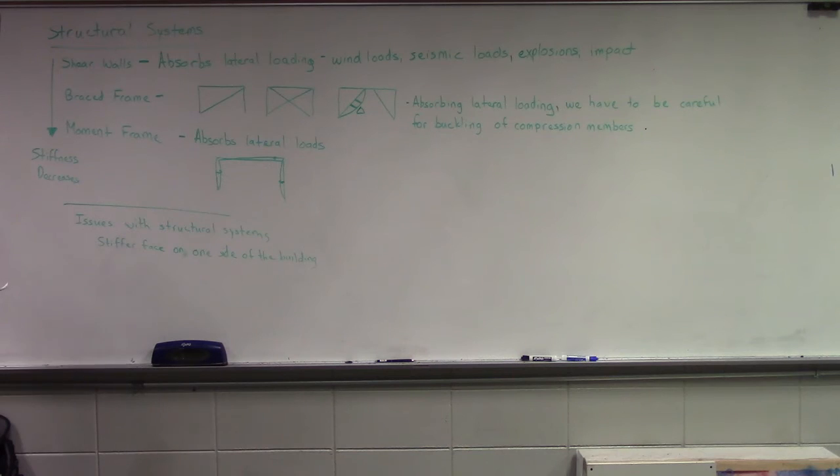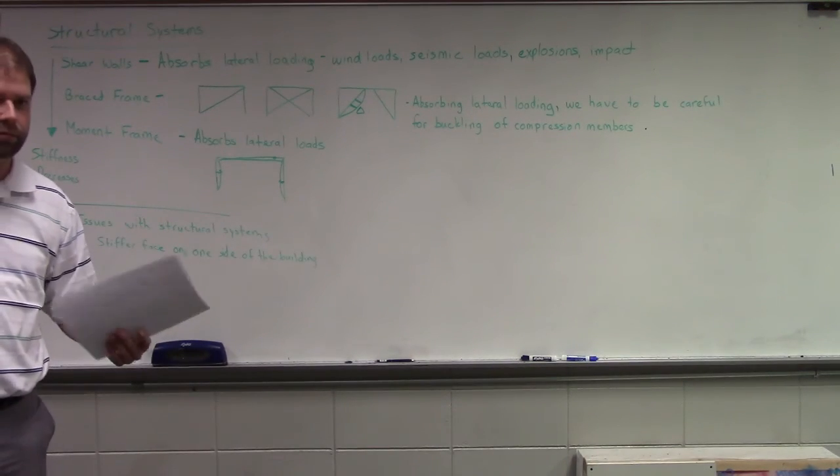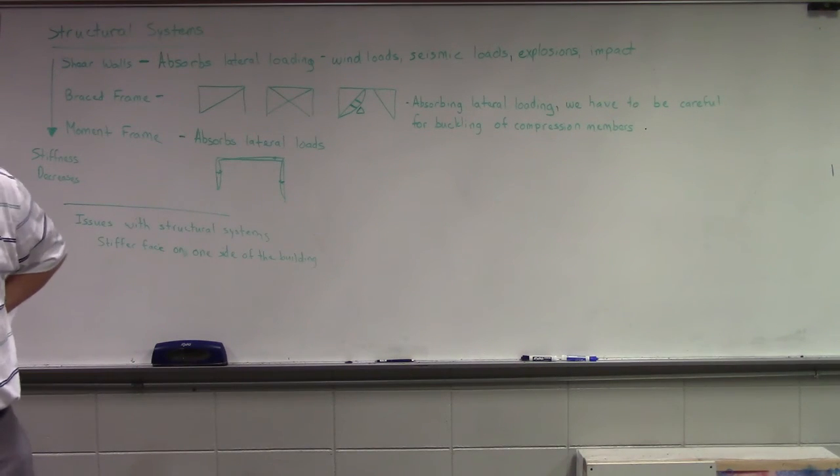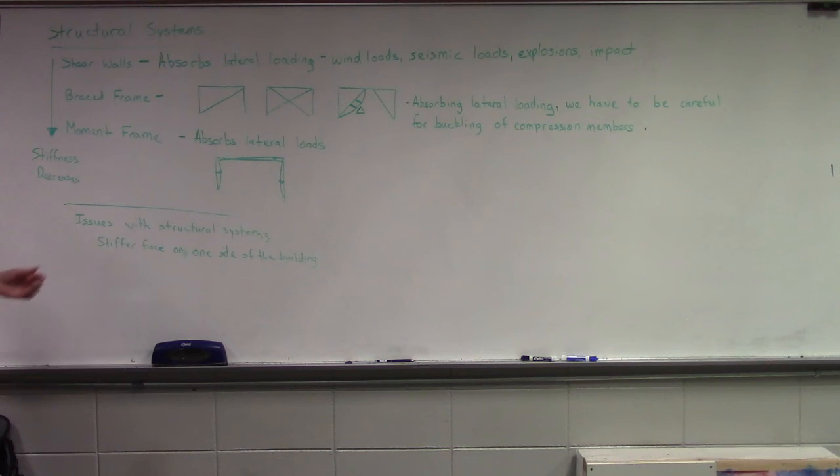If we're dealing with a timber frame or a wood frame, and we've got sheetrock in there, we're maybe cracking our sheetrock. So probably not getting us into huge structural issues, but it's certainly going to give us problems from an aesthetic standpoint. Still leads to a pissed off owner, right? Which is what we try to avoid.